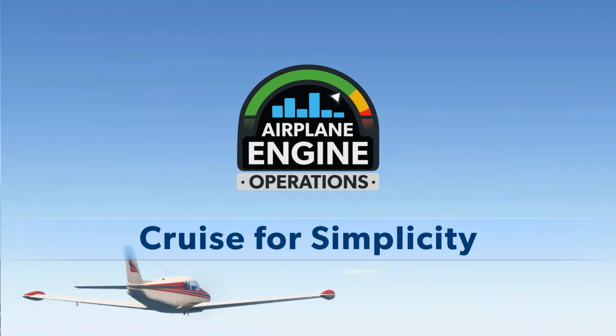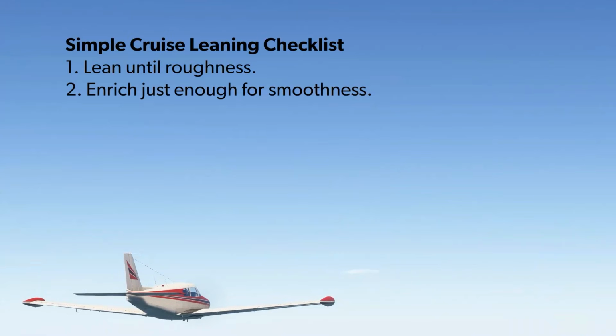And so this is a back to basics, old school technique. This is probably something that you may have been taught from the very beginning for how to lean for cruise, if you were taught to lean at all. So your simple cruise leaning checklist goes like this. First of all, lean until you experience some roughness. And then step 2 is enrich just enough to make the roughness go away. So really we're getting the engine as lean as it can go while still running smoothly.